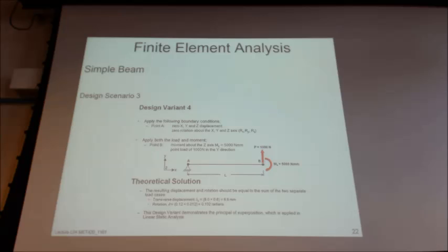So our final scenario, we'll put the moment on there and the load. And let's see, I have my setup correct, but my slide values are, hey, I got this one right. So we got our 8.6 millimeters. Again, I have left the shear in, I didn't take it out. So we're slightly different on the displacement versus our theoretical. For our rotation, this is the correct rotation, it's just a long slide picture anyway.